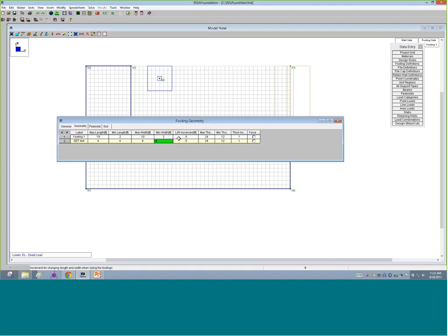So we've got here an increment. If we are going between these sizes, we can increment this length to width ratio. How often do I want to go? So I'm going to start at 2 and then move up by half a foot. So 2.5, then 3, 3.5, and so on. Again, the same thing for thickness. We're sizing that thickness from a minimum to a maximum in here. Same thing, if I know I just really want to check a 12 by 12 inch thickness, I can just set that to be the equal numbers and it will use that. And the same kind of increment. We can move up by 1 inch from there.